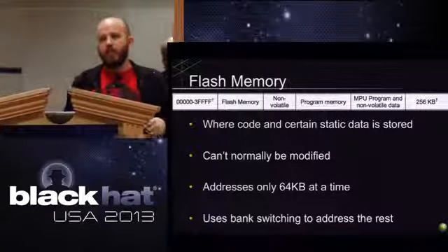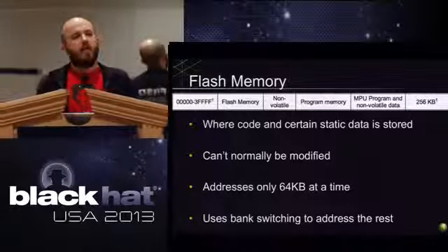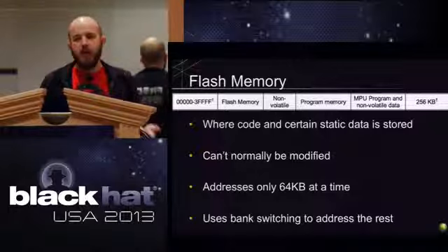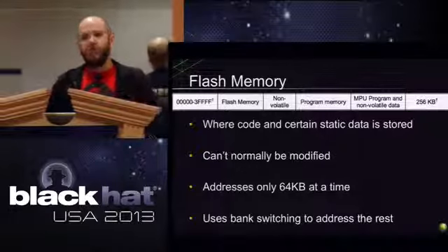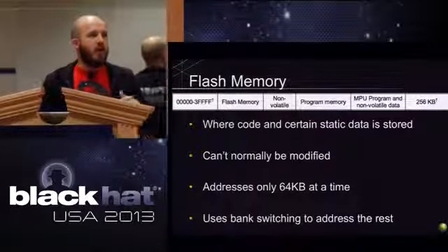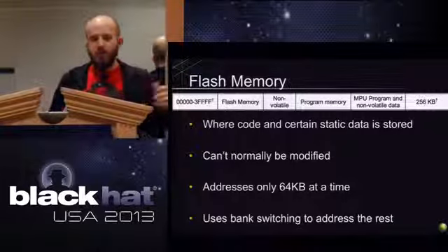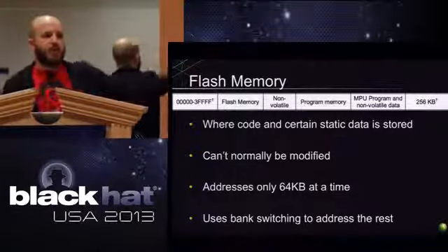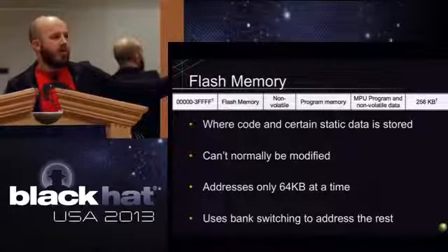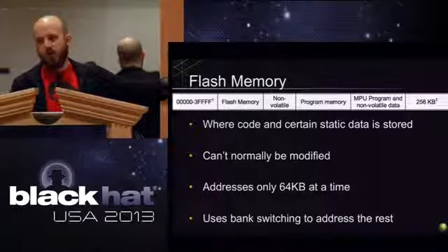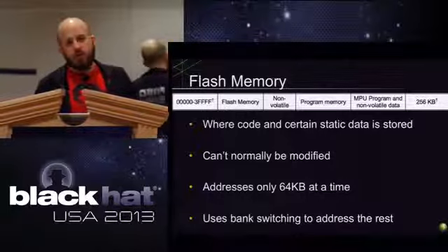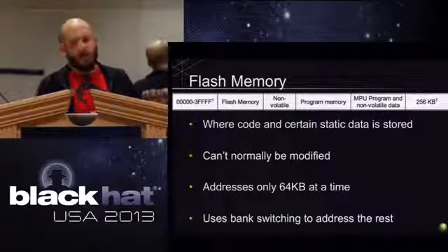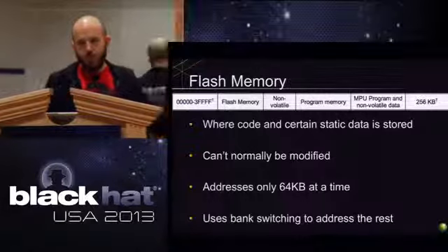So in the real world, nowadays Harvard architectures require the ability to somehow modify flash memory, and you have to jump through about 10 different hoops to make that occur. But the general statement is that you can't modify it. So that makes it hard. If that's the only place that instructions are ever run from, and you want to drop shellcode on it and do whatever you want to do, that is obviously the major barrier on Harvard architecture.